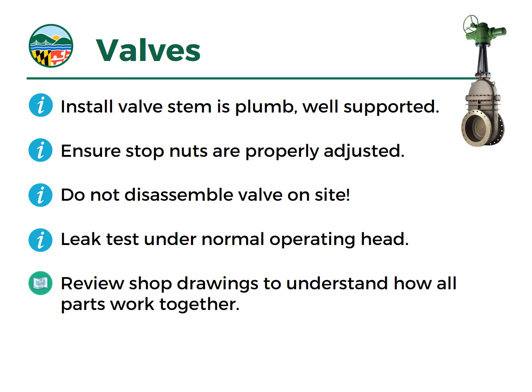So don't disassemble the valves on the site. And do perform leak tests. We want to make sure the valve leaks in accordance with, usually, an AWWA standard, because excessive leakage can result in loss of your pond. If it's drinking water or something like that, water is valuable. But that leakage can also cause damage and wear to your valve and the conduit structures as well.